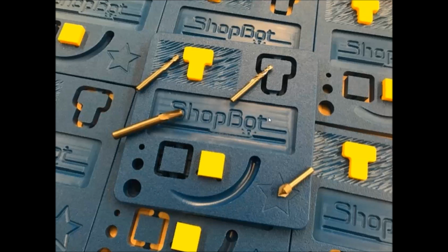We did several pockets throughout today. We did them where they were not just a pocket to a depth, like right here where the ShopBot was, but we did a through pocket over here with the holes. We used the Inlay toolpath to do a male and a female part, which is a profile toolpath and a pocket toolpath that fit together. The Inlay toolpath in the software allows it to mate together with the bit. You just make sure that you select the same bit for both the male and the female portion of the inlay.